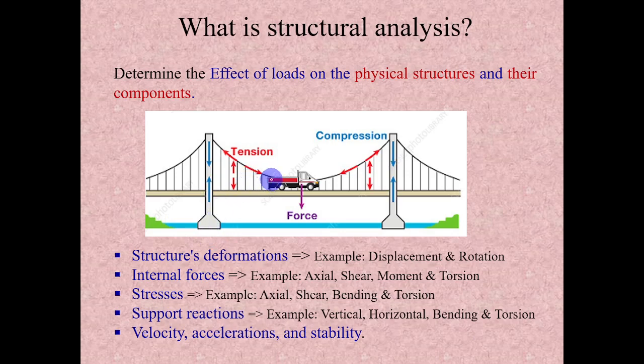Since this traffic load is a dynamic load, when it starts moving from left to right or right to left, the structure will have some natural frequency. So based on this dynamic load, this structure will go through some vibration, and due to this vibration it will also experience some velocity and acceleration.